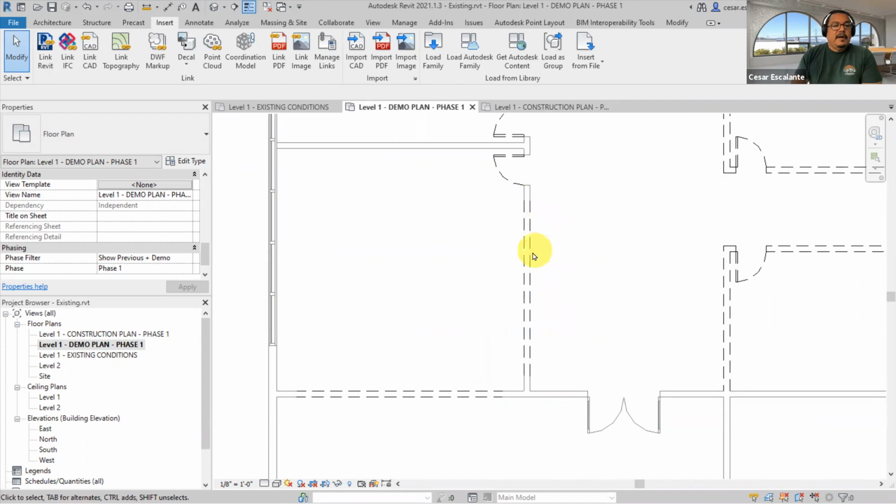Revit is going to identify the location and it's going to identify when openings are needed in preparation for new construction. So these 2 walls need openings, and Revit knows that based on the family, and it highlights for you when you need to create an opening for a new window.